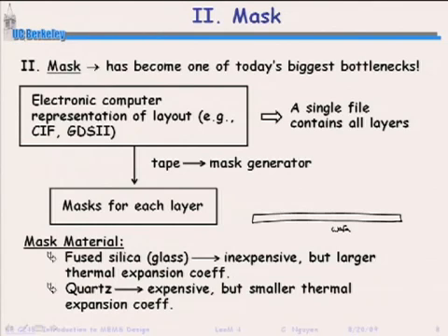Now you want to use a mask, using this lithography process that we just talked about, that you're going to put over this wafer. And you want this mask to align something exactly on top of the features that were already on your wafer. If this was the situation that I've just drawn, this is perfect.